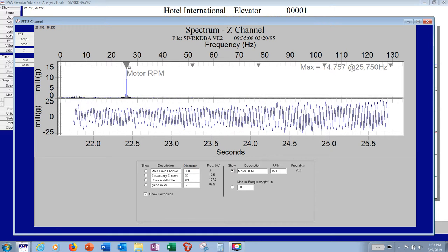So it's important to keep in mind that what you measure in the car is a summation of everything that's happening in the system. We're looking for either horizontal sources or vertical sources. In this case, the vertical source was a gearbox. It's a good way to identify where the problems are, and we can just simply do it by measuring on the floor of the car.